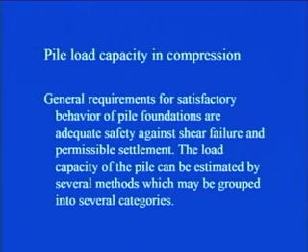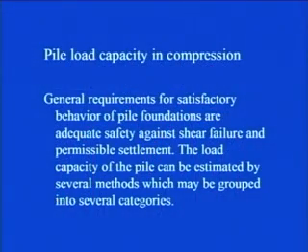In general, the general requirements for satisfactory behavior of pile foundations are adequate safety against shear failure and permissible settlement. The load capacity of pile can be estimated by several methods, which may be grouped into several categories. As in the case of shallow foundation, when you were checking the ultimate bearing capacity as well as the settlement criteria, likewise in the case of pile foundation also, you have to see to it that the pile is not failing against shear as well as not undergoing excessive settlement.